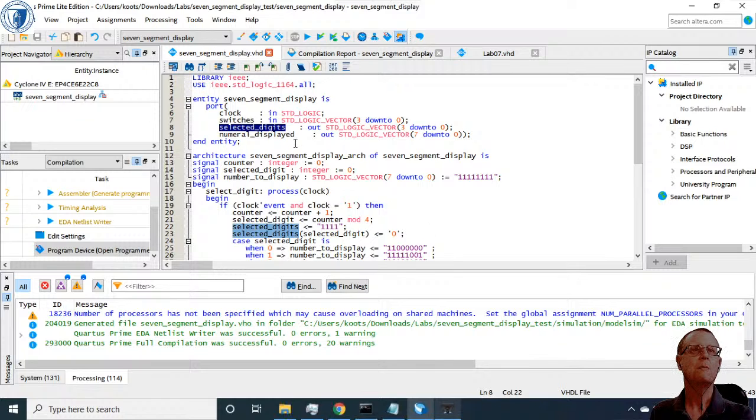Okay, so this is the 8 bits that determines the numeral I'm going to display on one of the digits, and then this is telling me which digits to make that display on. So initially I set all of them to 1, which means it's active low, so that means they're all off.